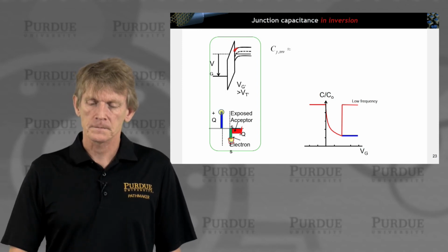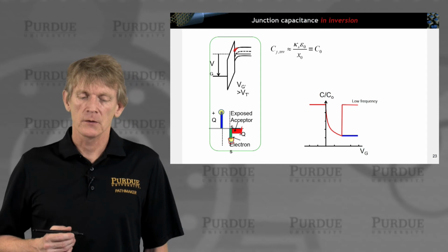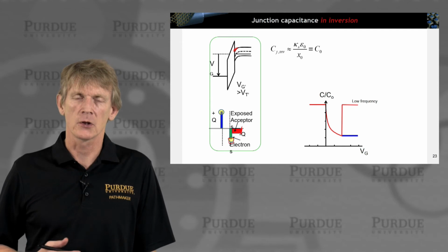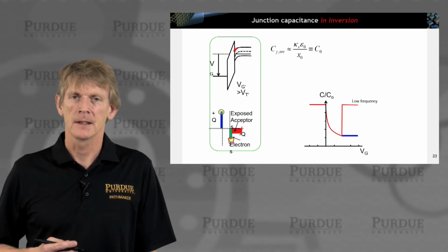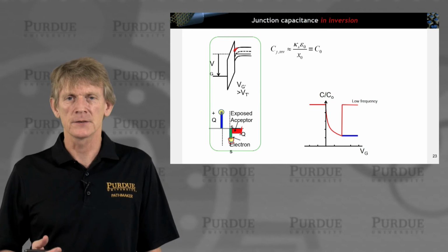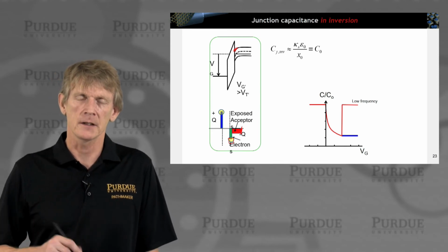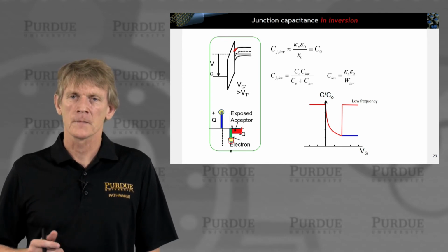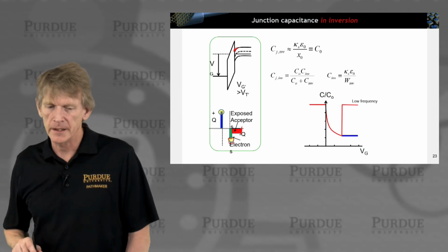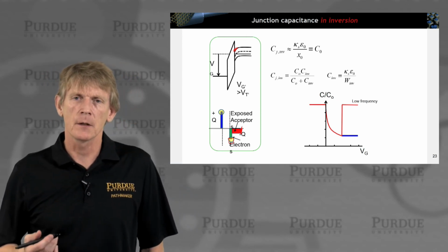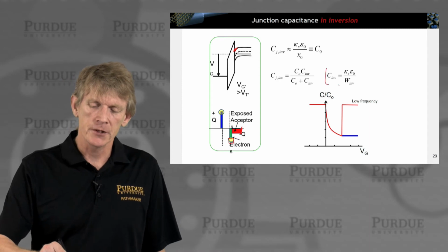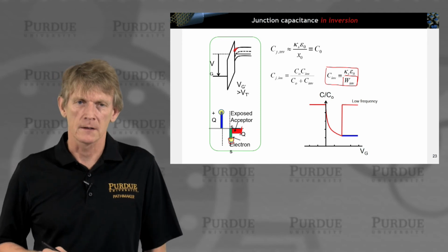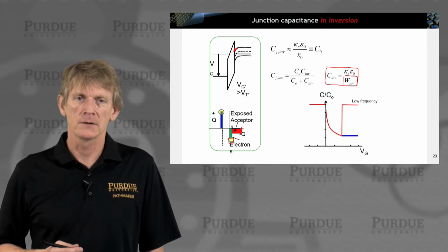Okay. All right. So that means roughly we are just again piling up charges like an accumulation close to the interface. Okay. And again, it's not exactly at the interface because the semiconductor has band bending, just like in the accumulation case. So we will introduce this series capacitance again, and we will have an inversion capacitance that has an effective inversion width that we distribute our electrons over.